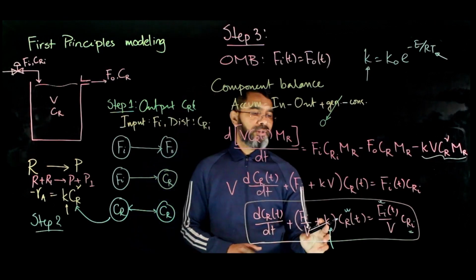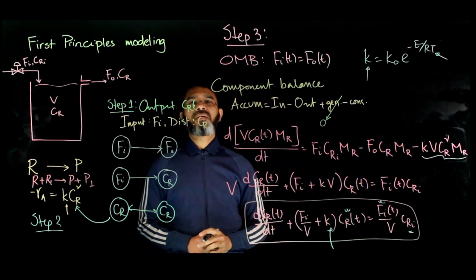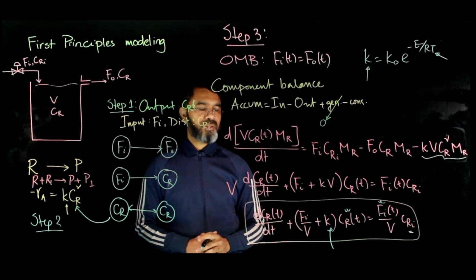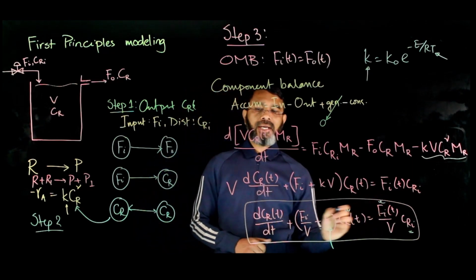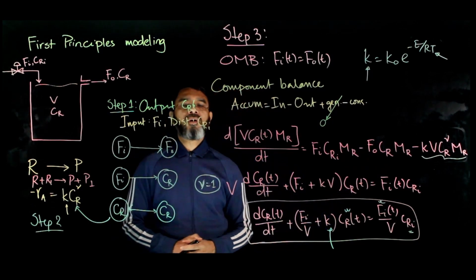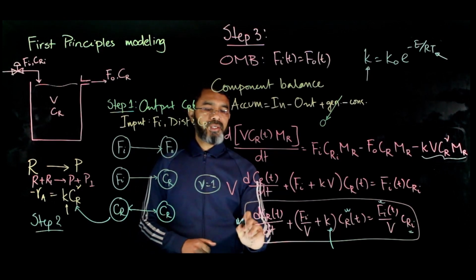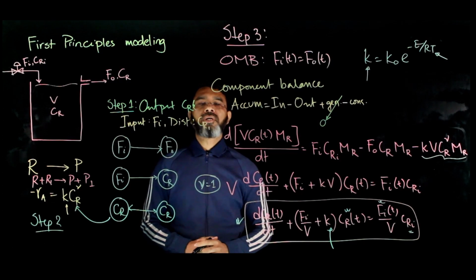Here that will result in a term with a nonlinear appearance of the temperature term that will need to be linearized. Now again, for this case, we have written it for a simplified case of reaction order 1. And the reaction can be of different orders and that needs to be taken care of. So finally, we get this equation relating the variables for the reactor case with constant holdup.